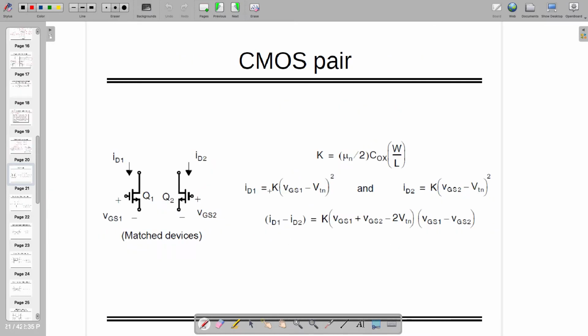If there are two different transistors and they're exactly matched, when we say matched, do you understand what we mean by matched? What is matching? Matching means carbon copy. Sometimes when I'm saying matched, it's not exactly a carbon copy. It's one side, let's say, multiplier m equal to 1, another side m equal to 3. By the way, W by L are exactly the same. I'm just playing with the multiplier so that they have matching geometry. That is also called matched, right?